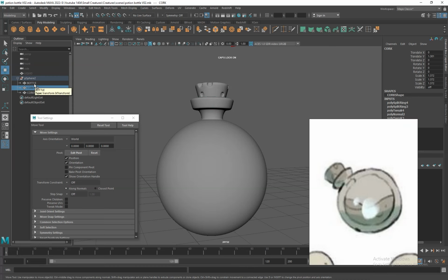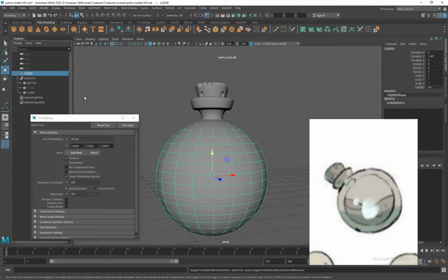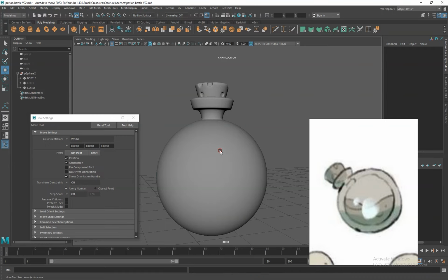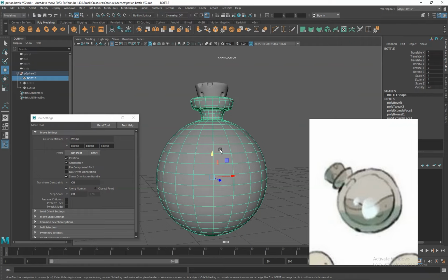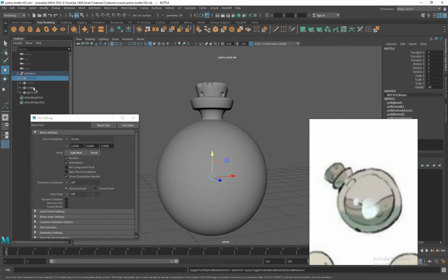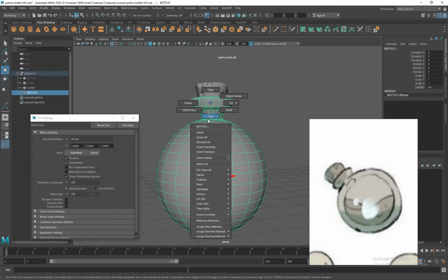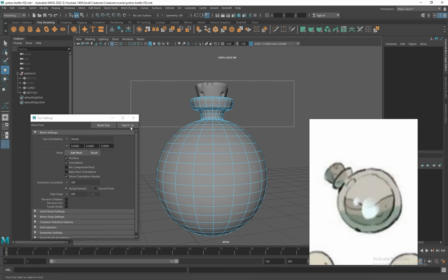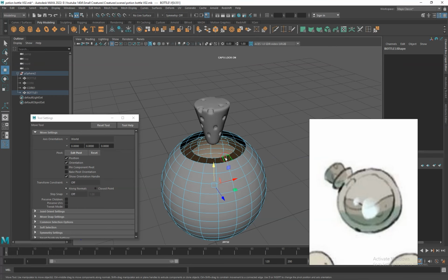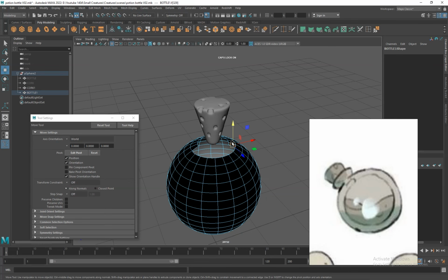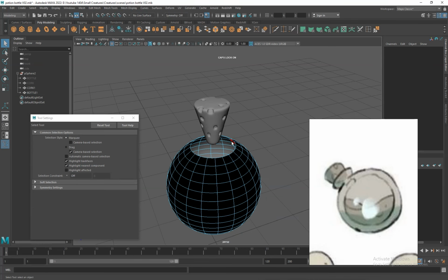Now let's make the liquid inside. Delete the previous liquid, it doesn't work. Instead, duplicate the bottle with Ctrl D and hide the original. In face mode, delete the top faces. We don't need them, and also delete outer shell or inward. Then reverse the faces.